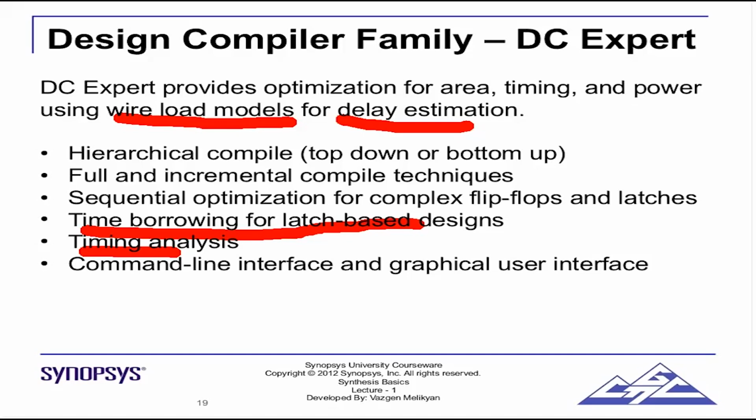First up, when we start any tool, we are tempted by the graphical user interface. But for tools like Design Compiler and PrimeTime, you would be heavily using the text-based interface. I personally favor the text-based interface because it gives a lot of reporting capabilities. The graphical user interface is only useful to see the circuit, but for a bigger design, you actually don't want to go into that until there is some very exceptional and big problem, because it will contain multi-million gates and you don't know where to start. So that's why I prefer text-based, the command line interface. It gives a lot of reporting capability.